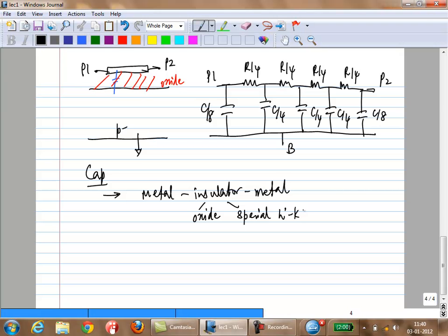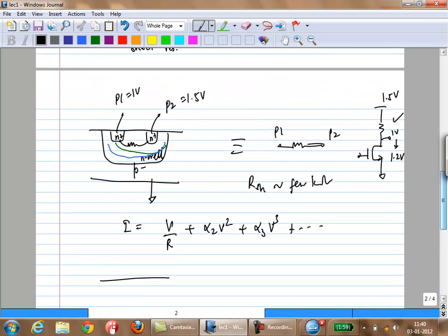It will be more linear than the N-well. Definitely more linear than the N-well, because with polysilicon you're interested in a very low resistivity, and it's not directly connected to the substrate. So you will have better linearity for sure than your N-well. Sorry, it depends on the value of the resistance you want. If you want only a few tens of ohms, your capacitance may be low enough. Remember that because the resistivity is low, if you want, let's say, hundreds of ohms, and you make a very long poly, you'll have a lot of capacitance because you have a lot of area under your poly. Is that clear? So obviously it depends on the particular application, the type of resistor you'll choose, and what is more important.